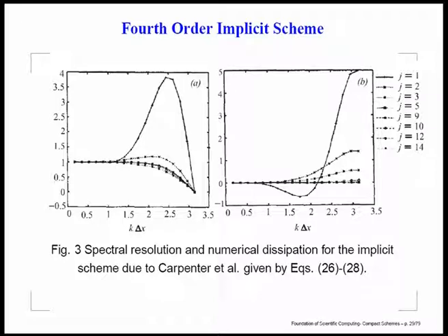So, what you see is that compact schemes or any discrete scheme has this attribute as we have plotted. We have seen that they have this tendency to make k equivalent by k go to 0 at pi. We have done it if we have looked at CD2 and CD4 expansion in the previous part. This is what happens. However, you notice one very interesting thing about this. At j equal to 1, that is the inflow part of the domain, look at this. It has a very exaggerated overshoot.